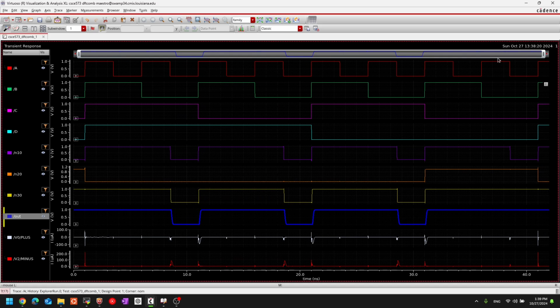You could go through all the combinations of the inputs and make sure whether the circuit is functionally right by going through the truth table of the circuit itself. Once you've made sure your circuit is functionally correct, you could go through the IDDQ analysis and see whether there is a problem or not.